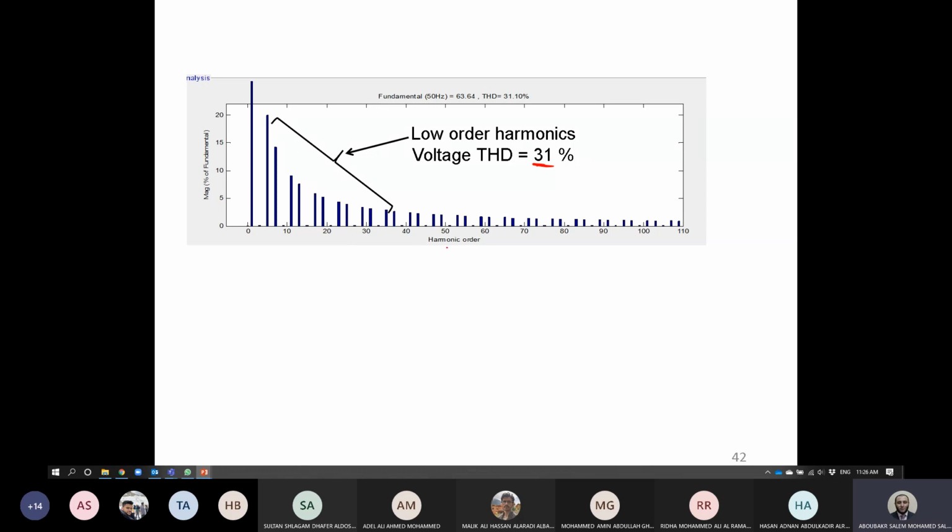So here we have harmonic order, Shabab. Harmonic order means if we said fundamental, so harmonic order is number 1. So this is now representing fundamental, and it's going to be up to 100%. We said before, we refer all of time the spectrum to the fundamental. So fundamental is going to be 100. So we cut it all of time in order to zoom in to see the harmonic contents in the low values.